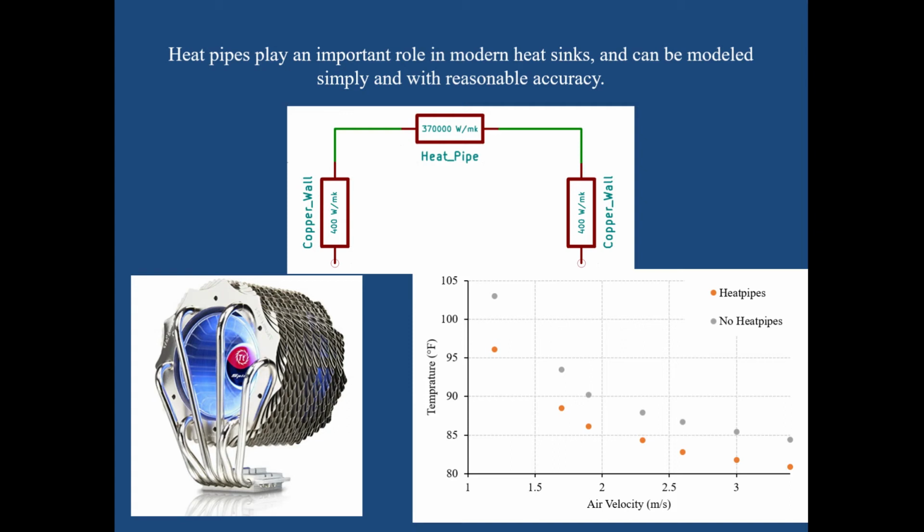This project was able to develop a method for analyzing a particular heat sink containing heat pipes. It was found that heat pipes can be modeled with a highly conductive solid core representing the phase change process. It was also demonstrated that heat pipes are effective at balancing out temperature distributions in a heat sink. As modern electronics continue to advance, improvements in heat pipes and their associated models will be required to dissipate their increased thermal output.